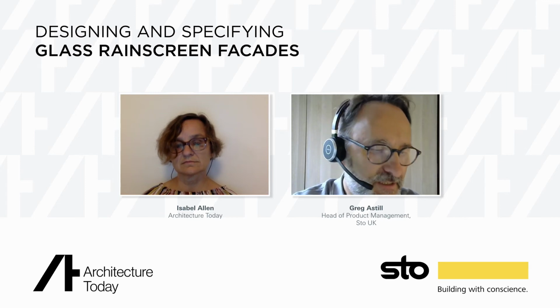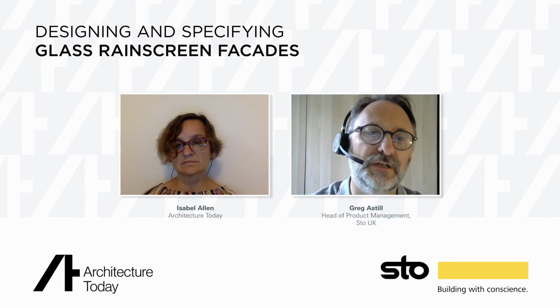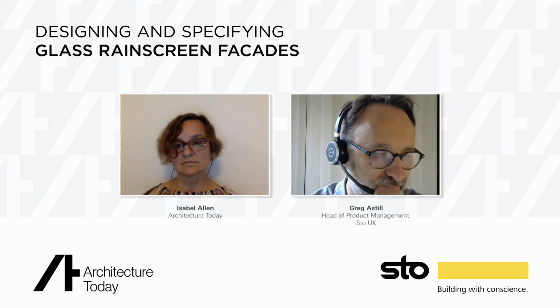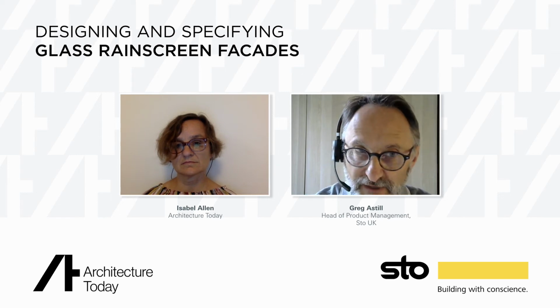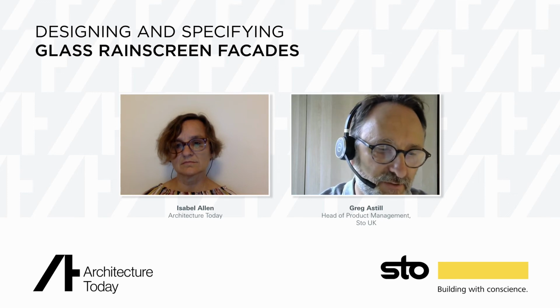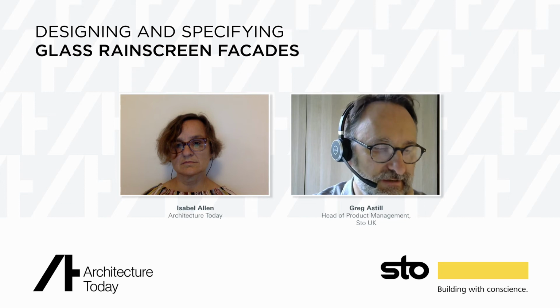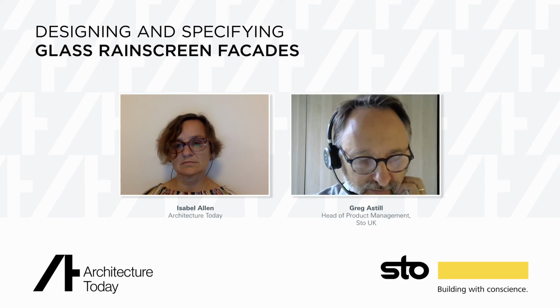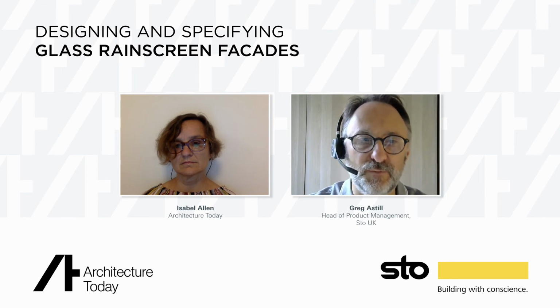So typically it's Part A, which is primarily where Rainscreen is concerned. It's to do with the wind load and supporting its self weight, its dead load. Then Part B is to do with fire, as we've just discussed. So it's to do with cavities and also the reaction to fire, restricting the external fire spread on the face of the building. And then finally, you've got Part C, which is concerned with resistance to the passage of rainwater.